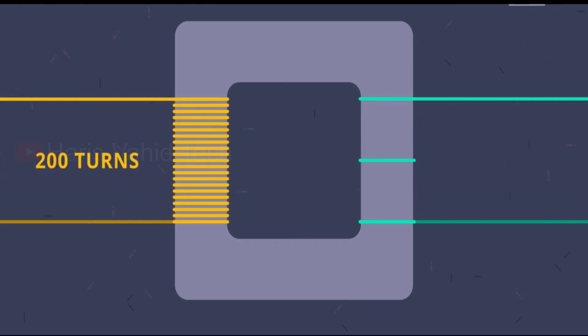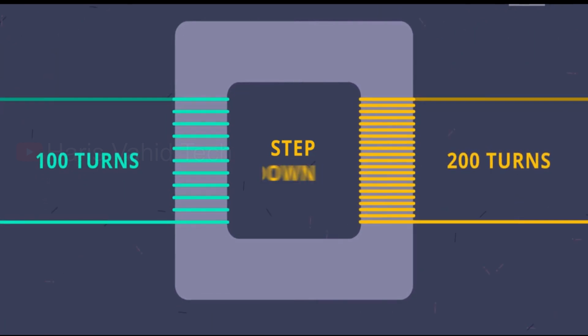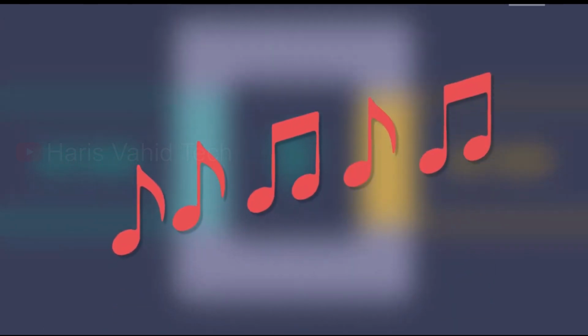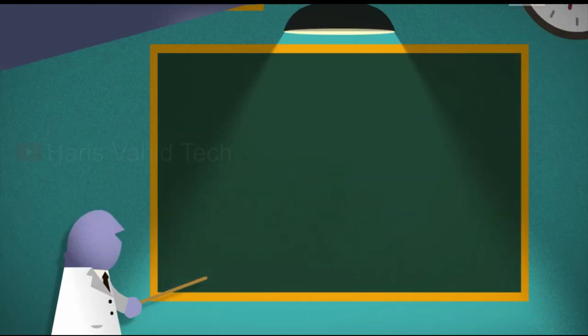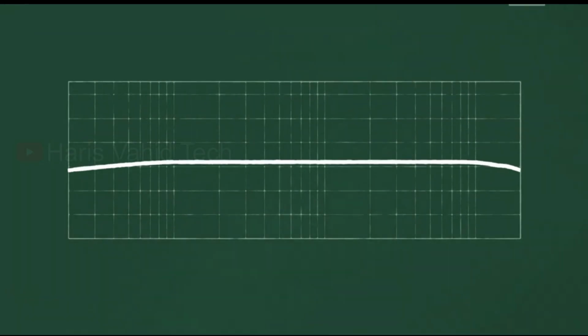Typically, 4 ohm, 8 ohm, or 16 ohm speakers are available, whereas transistors or solid state amplifiers use 200 to 300 ohms output impedance. If the amplifier is a retro design, such as an old valve or tube amplifier, then the output voltage sometimes reaches 300 volts with 3k impedance. So, we need impedance matching transformers which will convert the high impedance to low impedance and should convert the voltage and current to a level which will directly drive the loudspeaker.